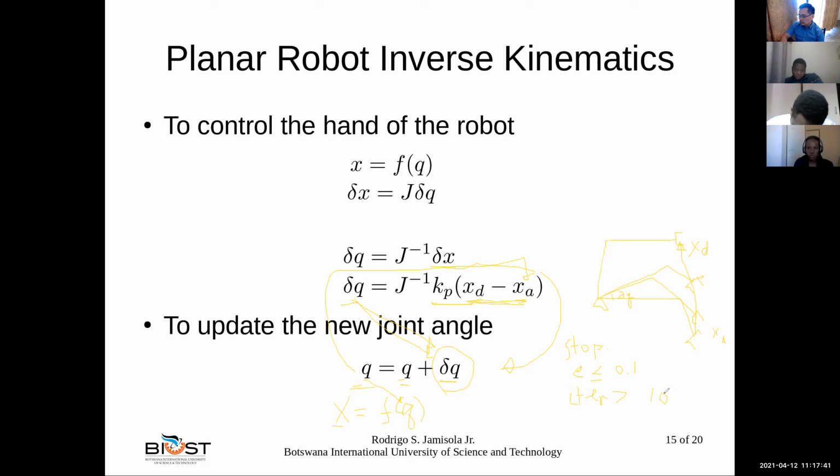Sometimes if you don't do that and the computation does not converge, meaning this error is not achieved, it will continue on and never stop computing. So you must have a maximum iteration count. Those two criteria will help you exit the iterative computation. Okay, let's clear all that.